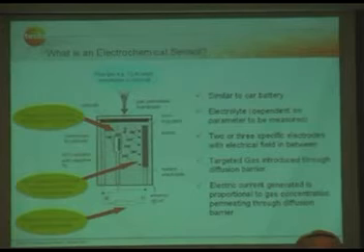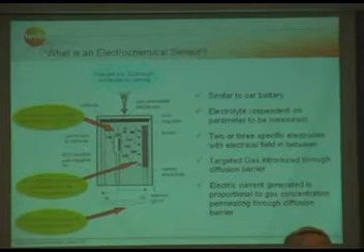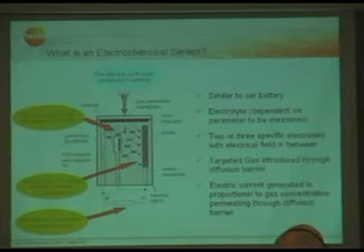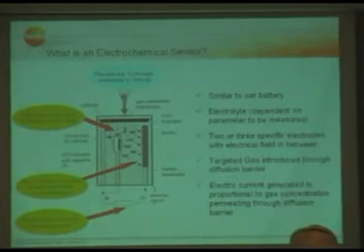Because if you don't use the sensors or the analyzer very often, the lifetime is still between 2 and 3 years, and then you have to replace the sensors, even if you don't use the instrument very often. This is something just for you to get the highest lifetime out of the analyzer and the sensors. If you don't use it, just switch it on after 4 weeks for a few minutes. Let the analyzer rinse and get fresh air through the sensors. Switch it off, and then you can expand the lifetime at least by a third.